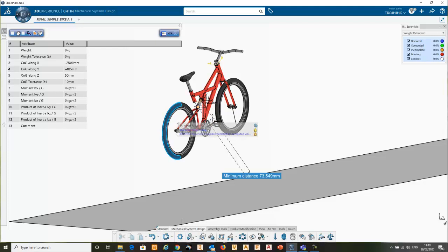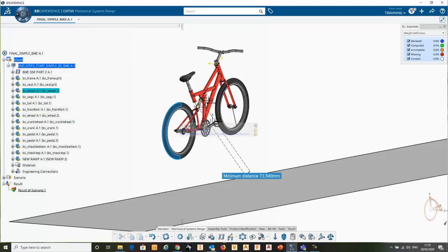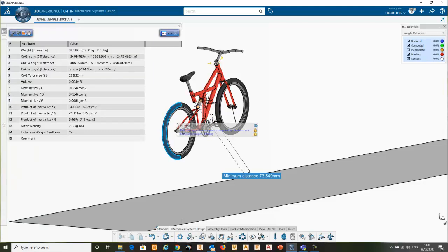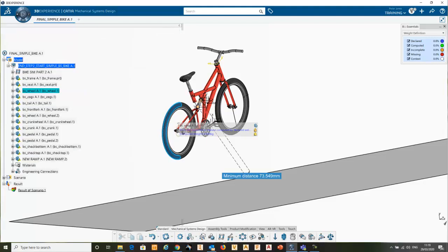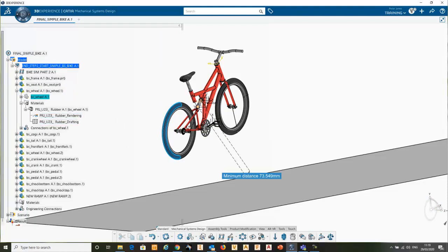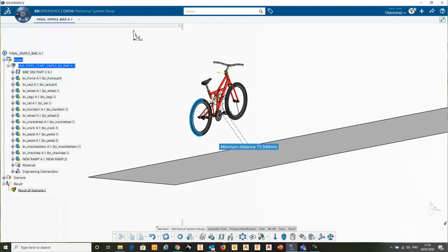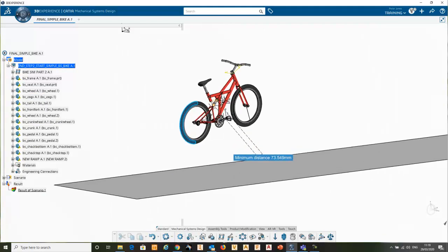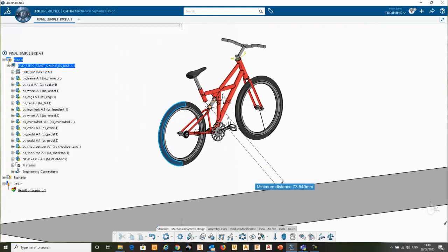So you really need to actually make sure that it's actually computing from the definition of the model properties. Now what I've done with this particular one, I'll be honest, I've put it in as rubber, but I've actually cheated by changing the density of the material to get that down to the right weight. Otherwise it's, you know, a little bit heavy. The model isn't particularly well defined in terms of applying the weights, but that's important that you do that.